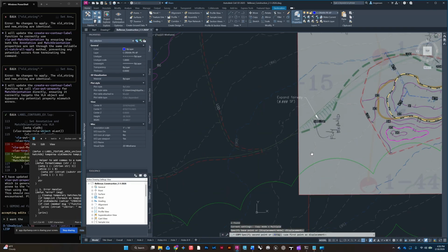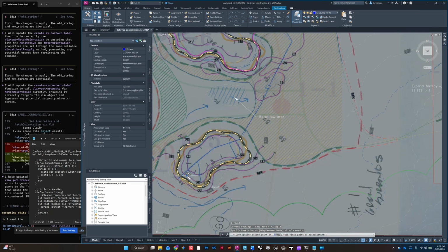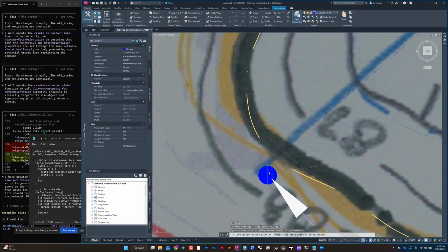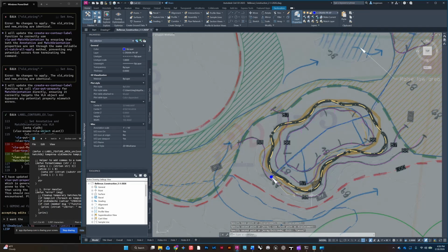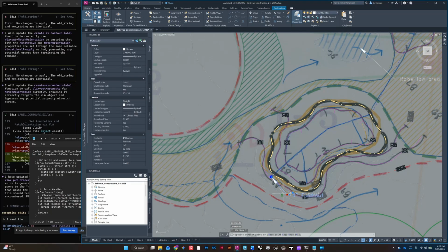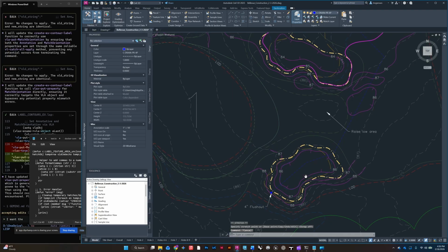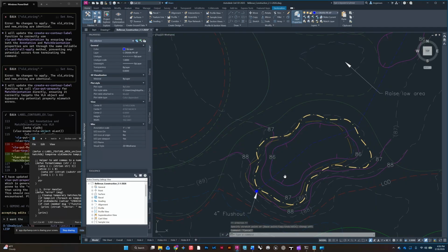CAD is designed to be precise, so there's no reason to just guess at what the center is. And then when you're putting it back down, snap it to that endpoint so that it's perfectly aligned. You can then move the body of this text somewhere that isn't in the way. And now there you go.